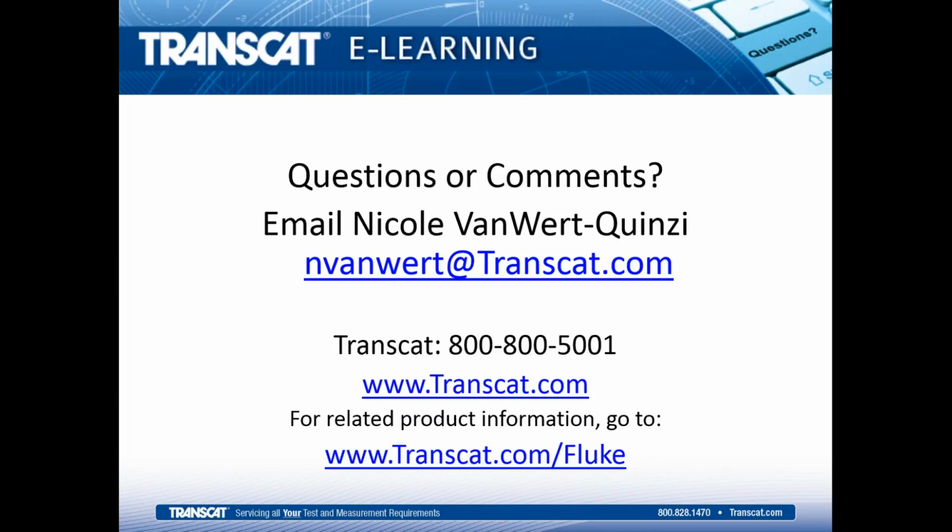So how can you measure uncertainty? Okay, well, I'm assuming that we're calibrating the 52 with the dry block calibrator, and so there is an additional component of uncertainty created by the low resolution of the Fluke 52. The 52 is not usually used in calibration, but it could be a good tool to calibrate, and you probably got it connected to a Type K thermometer. What you would do then is, to all the other uncertainties that were listed, also add an uncertainty for the resolution.